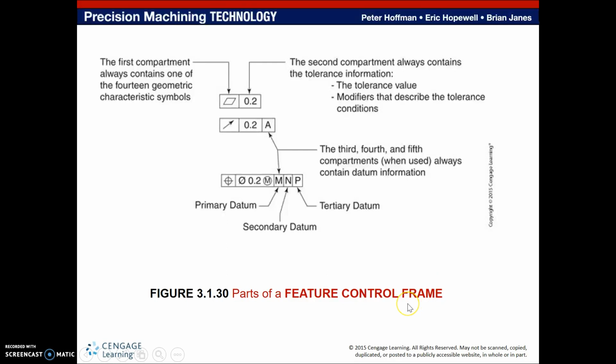So in working with geometric dimensioning and tolerancing, we spec this out on a detailed drawing using what's known as feature control frames. And here you can see an example of a feature control frame right here. Notice that this is the geometric dimensioning and tolerancing callout. Now, something to know about your feature control frame: this doesn't tell you anything about the size of the hole.